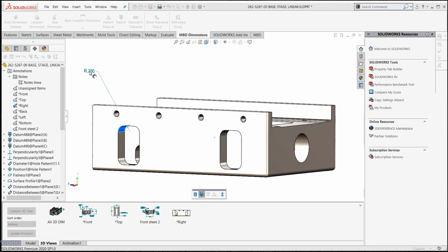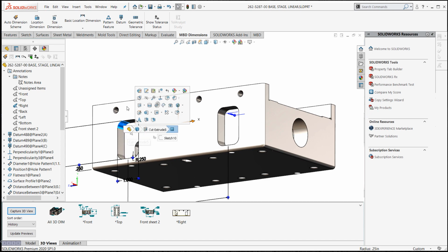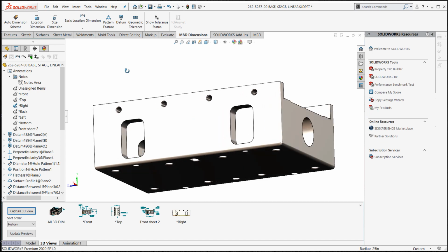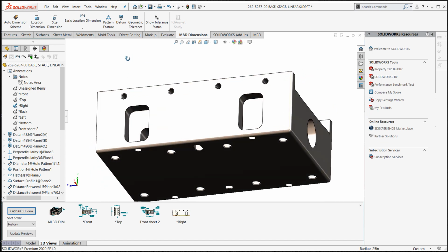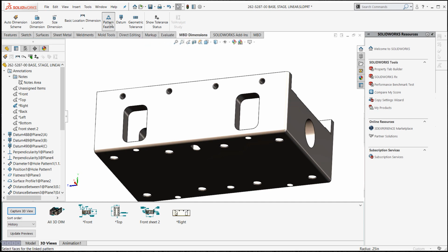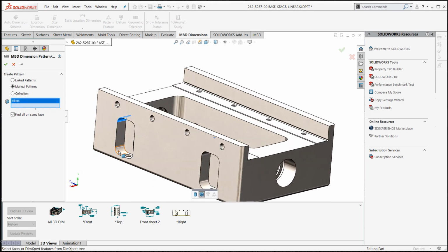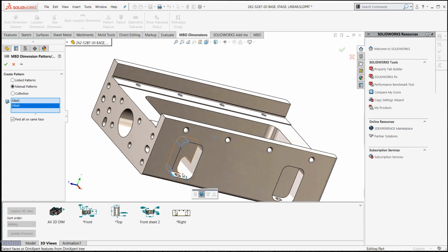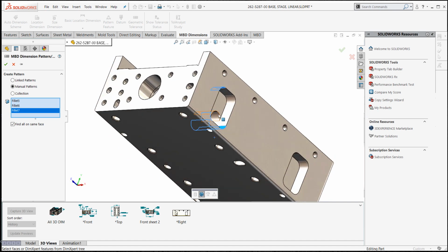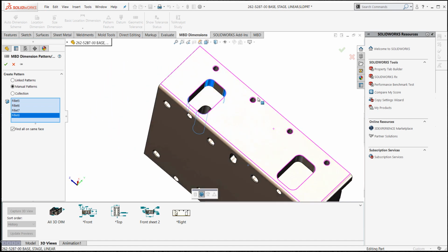As stated in the beginning of the video, you click, and this was created using a sketched fillet, and then the sketch was mirrored over, and we've got all sorts of non-related fillets there. So how do we go back in and relate those fillets? Well, we go back into pattern feature, and then we go to the manual. I can do this anytime along the process. Collect all the fillets.